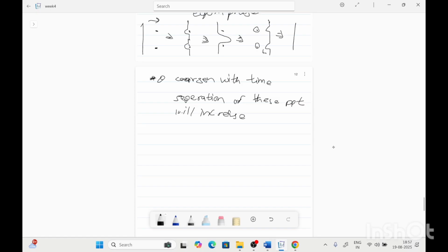So due to this increase in distance between the precipitates, the dislocation can easily go through it and will face no force during the motion, and that will reduce the hardness when the theta precipitate coarsens.